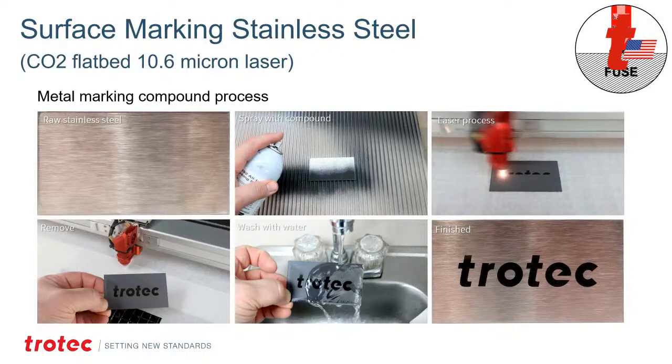It's a clay-based compound, a molybdenum trioxide type sandy material, and so you can wash it right down the drain safely. And then once you're finished, you're going to actually have that fused mark, and that finished fused mark is a high contrast. If you look under a microscope, it actually looks like little beads of glass have been melted to the surface of the metal, and that's in essence what it is. So this is an extremely popular process. It doesn't require the additional cost of a fiber laser or a Galvo fiber laser.